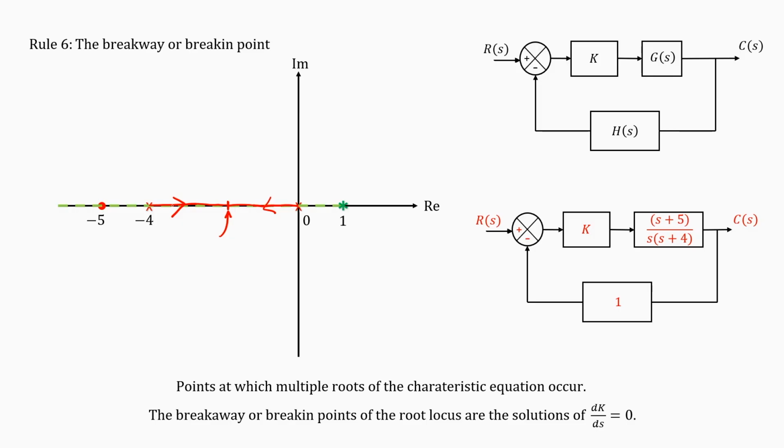There are two poles. Again, what is root locus? Again, I am just recapping things. Suppose I say this point is a closed loop pole. Now, this satisfies the angle criteria, right; the rules that we are using are only angle criteria. So, this point is a closed loop pole. If this is a closed loop pole, then we must have a value of k at which this is satisfied, because it satisfies the angle criteria. Now, I can use the magnitude criteria to find out the value of k.